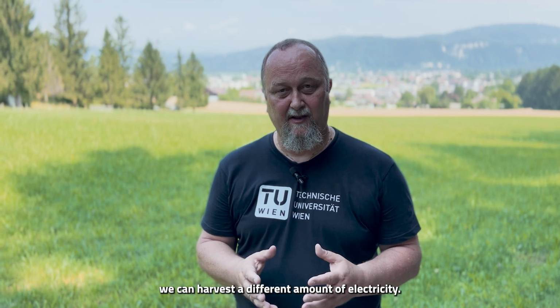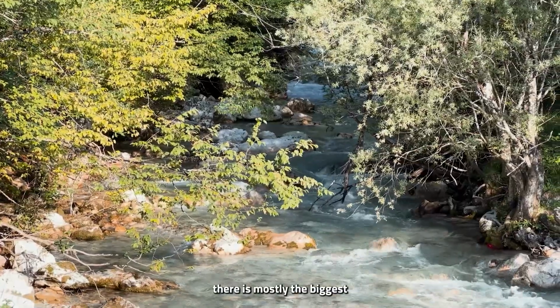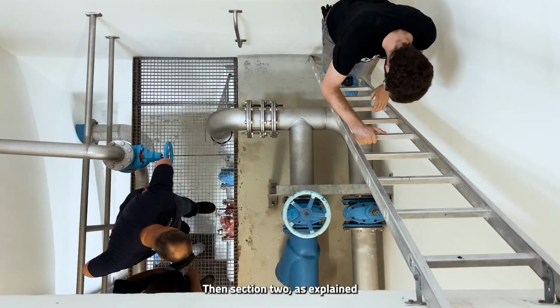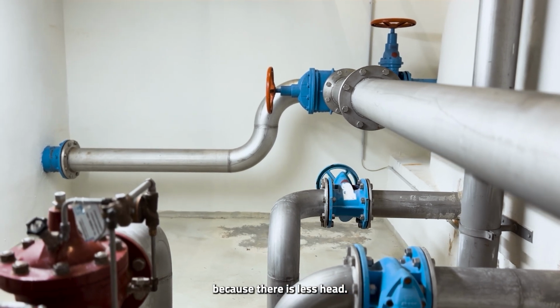Within each section, we can harvest a different amount of electricity. From the spring to the reservoir, there is mostly the biggest possibility of energy production. We are talking of several hundred kilowatts. Then section 2, as explained, between the reservoirs, there is less potential because there is less head.